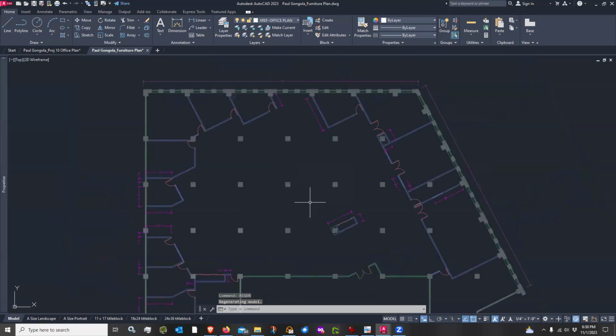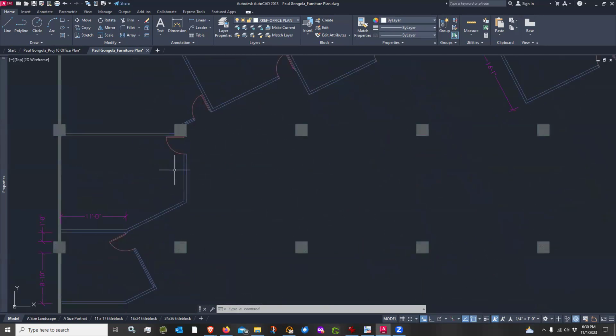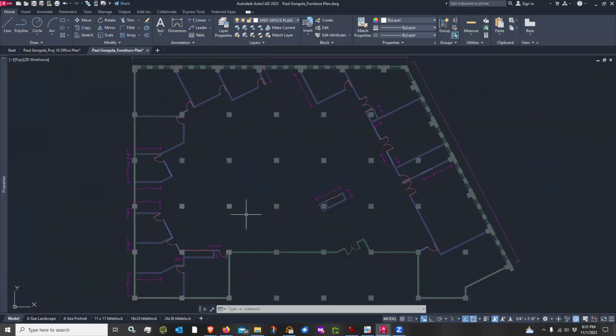And I don't have any dashed lines on here, so it's not going to really do anything. But that is just a reminder that you can change the visibility. If your dashed lines like mine weren't showing up, you can use MSLT scale. That's a good command. Have it in your notebook or in the back of your mind, and just remember it forever until AutoCAD wises up and just by default turns it on, but they don't. So, okay.